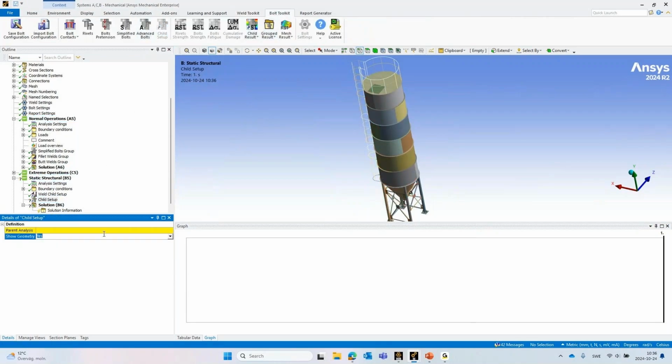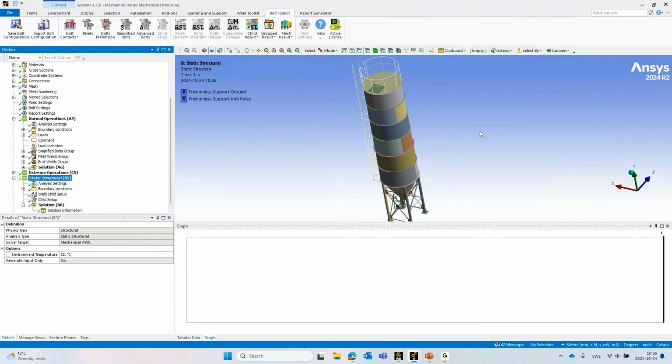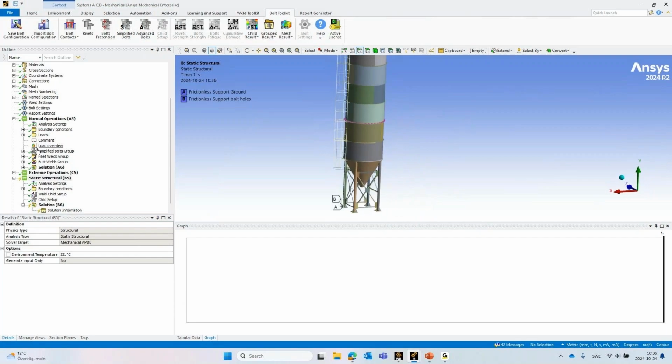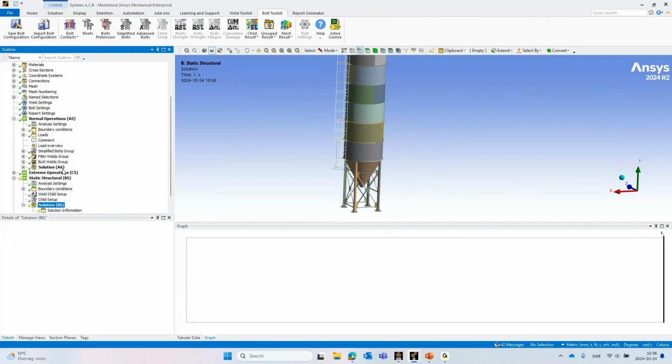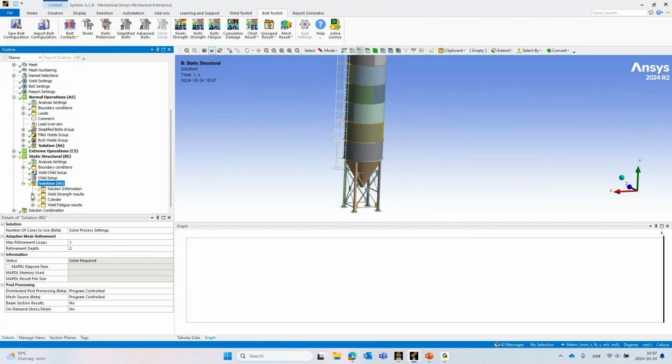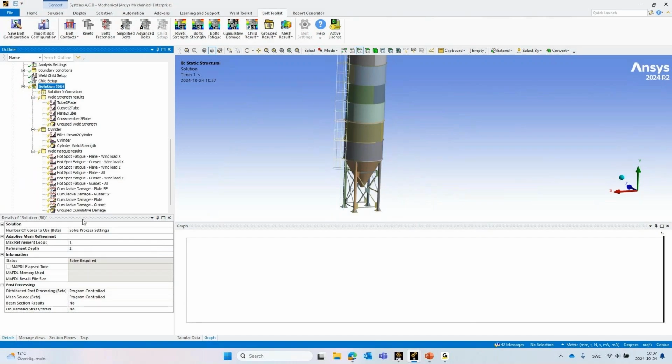So quickly selecting here. So now this model is set up in exactly the same way, and will be, if I change the bolts and welds in the first analysis, the linked analysis will have the same settings directly. And I can now, with a click of a button, import all the weld results from this parent analysis. And we get here directly grouped in the same way, linked to this analysis. All the settings are now the same.